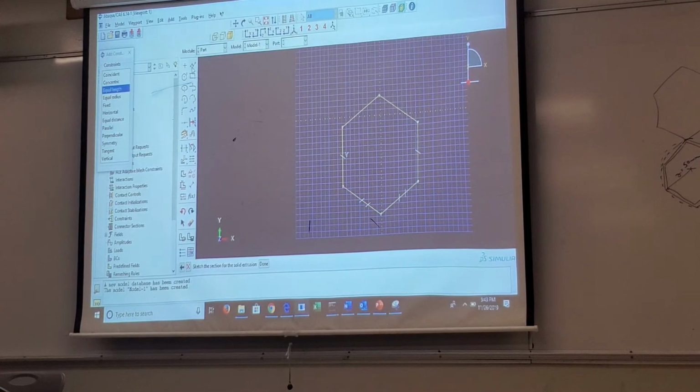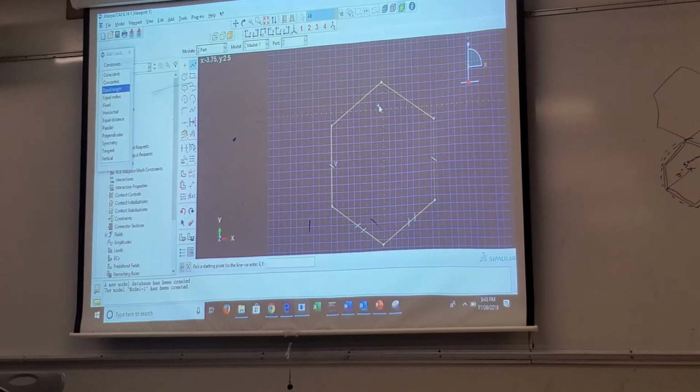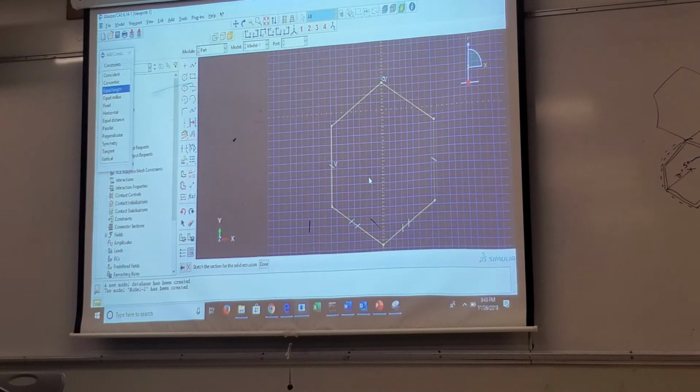Once that is done, then pick this line feature, and before you pick the line feature, select this option, which is create construction lines. So in this create construction lines, if you keep on clicking, or if you press the click button, you will see the option for vertical lines. So what I am going to do, I will just create a construction line like that. Okay. So first I created a hexagon, then I deleted the outer circle, then I create this vertical construction line.